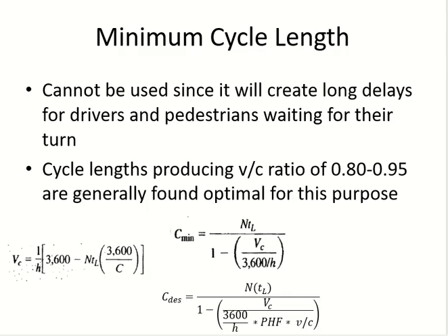Now let's say we came up with this design, and people in the ministry said that the road space is limited. So you are asking for 3 lanes here, but we can only give you 2 lanes. So if I make 2 lanes here, in the 1800 direction, 1800 divided by 2, which becomes 900. So my VC will be how much?